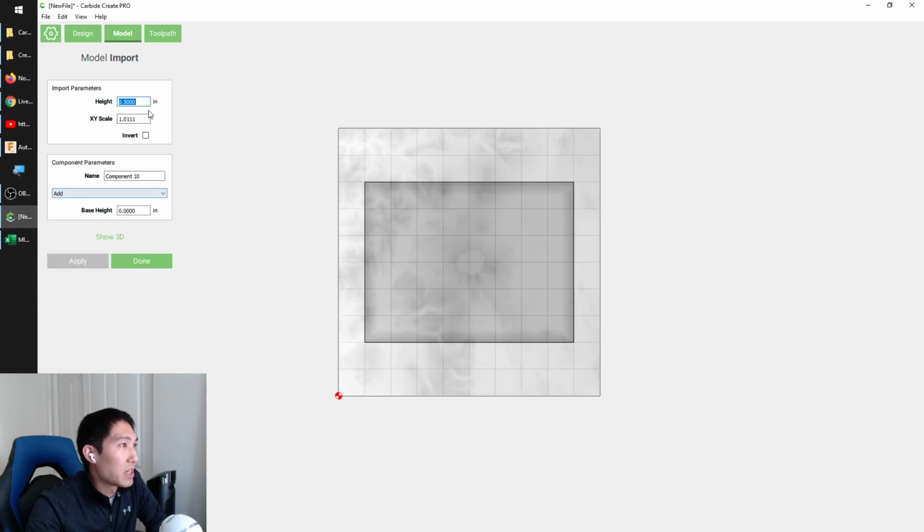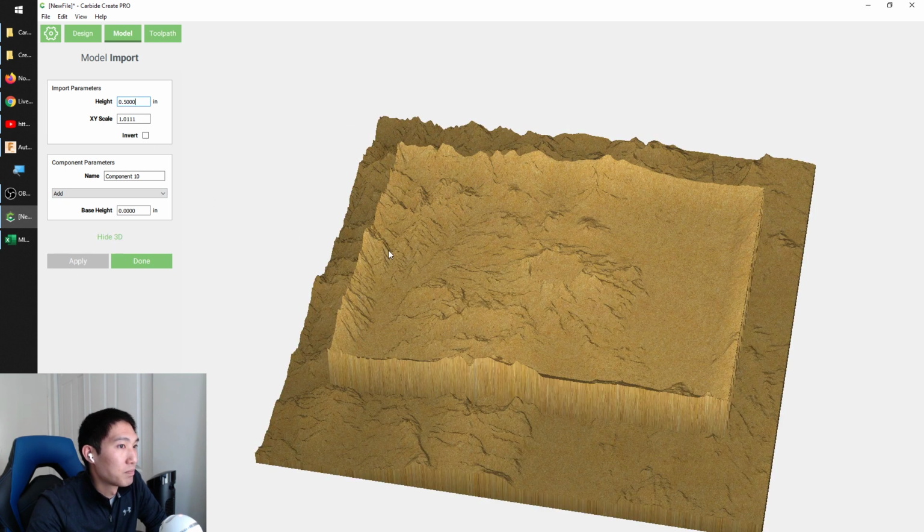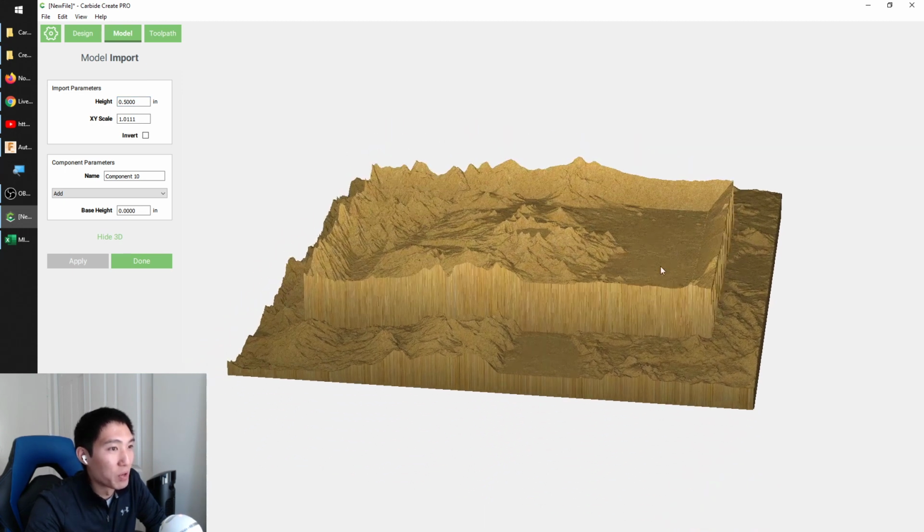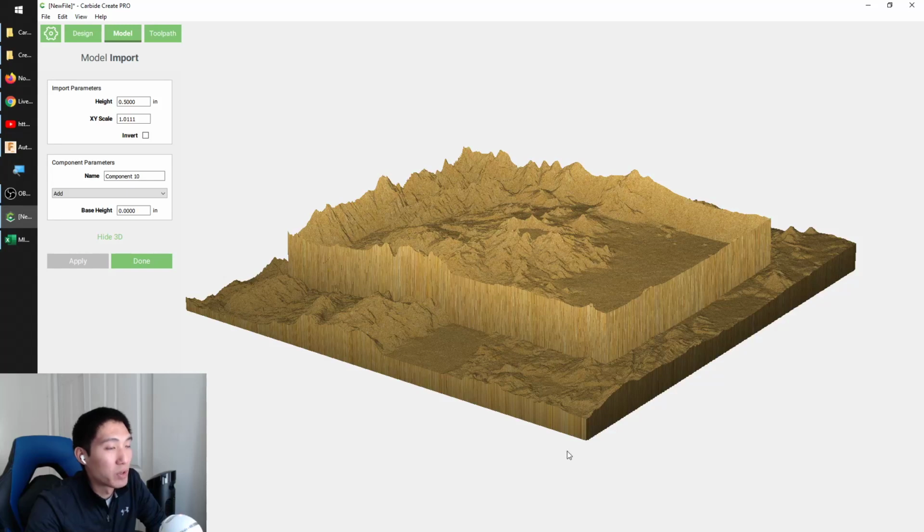Let's say height scaling 0.5. Sure. I had the previous features there, but you can sort of see how you would build up a height map. You would do this ideally with a little extra stock built up underneath it, so you're not cutting through to the bottom of your wasteboard. But yeah, weird, intricate carvings, decorative flourishes, topographic carvings.